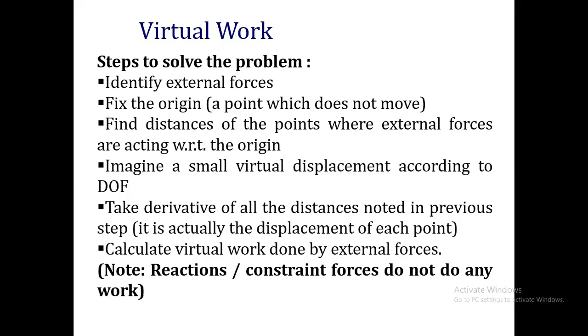Then the next step is to fix the origin or a reference point. A reference point is one which does not move. According to the type of support, we need to make a proper choice of origin. Our next task is to identify the points at which external forces are acting and determine the distance of these points from the reference point, the point of origin. These points will be given a small virtual displacement in accordance with the degree of freedom.